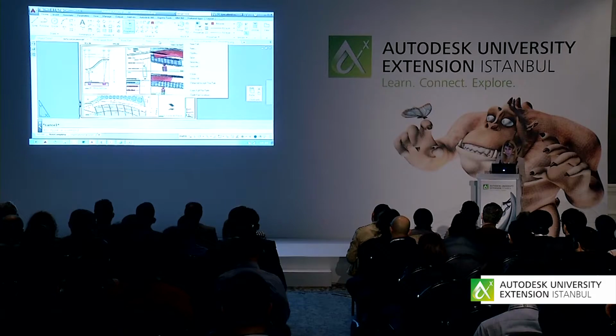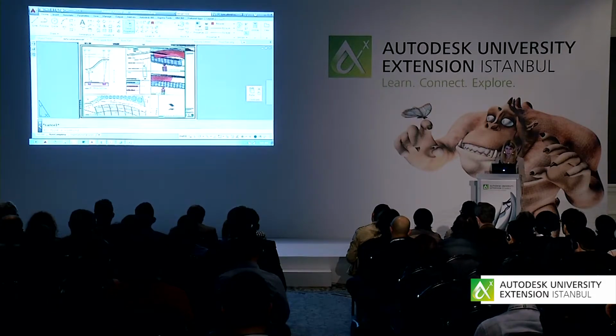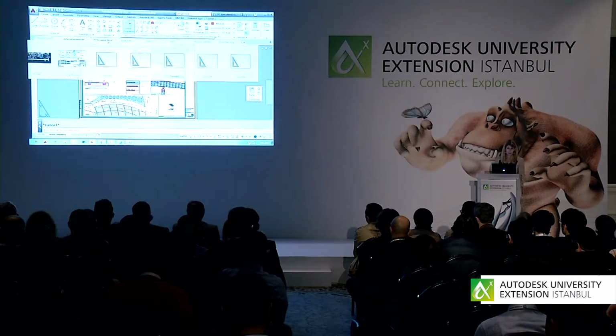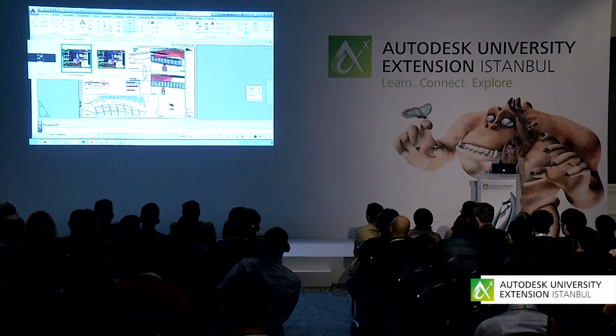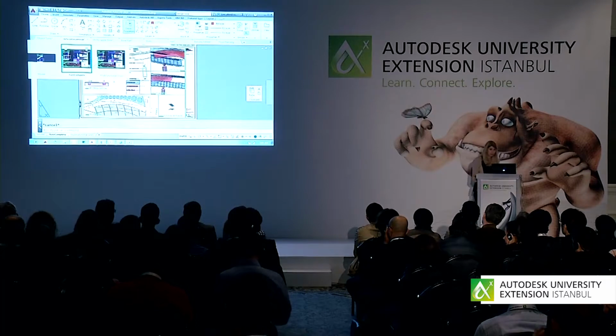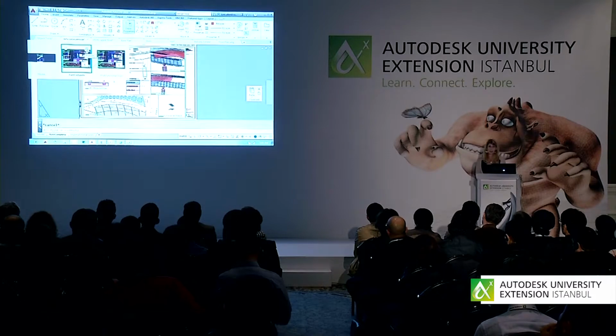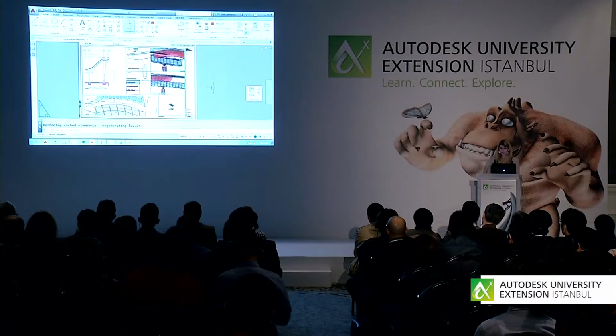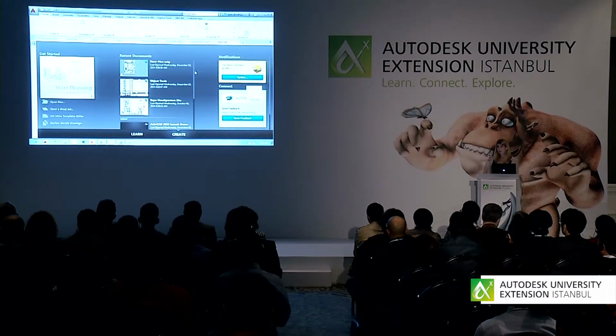You'll also see as I move my cursor over the tabs that it shows you the various layouts, which is very nice. I can actually move my cursor to one of the layouts, and you'll see that conveniently I can very quickly plot or print the layout without ever having to actually go to it, which is nice. That's just a preview. It doesn't actually move me there. And you'll also see, if you click on the plus, that takes you into New tab, and you can continue to add new drawing files.